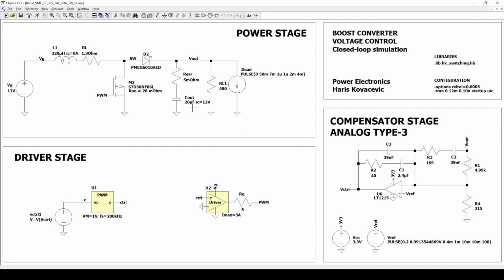And now we have the real power stage. The inductor current is no longer averaged. It ramps up and down every switching cycle, and the MOSFET and diode switch continuously. This introduces switching ripple and makes the system behavior closer to real hardware.